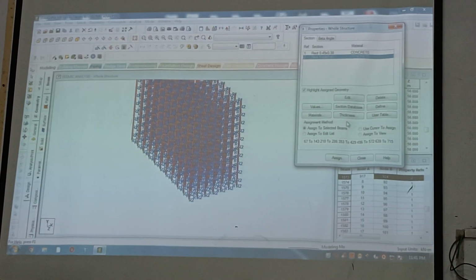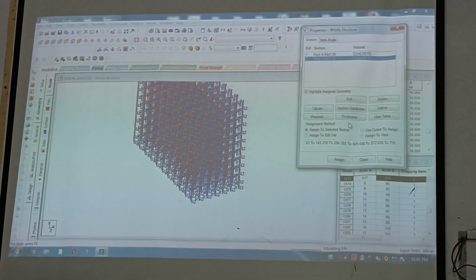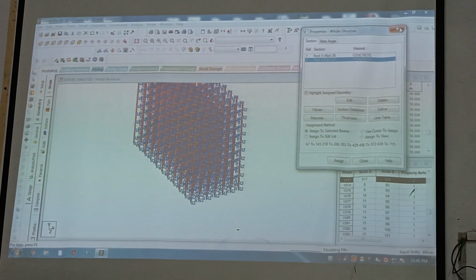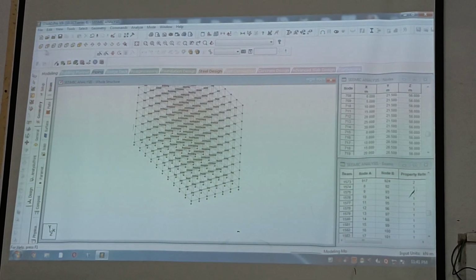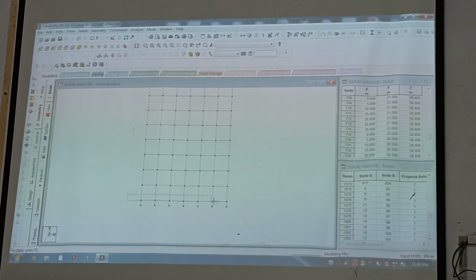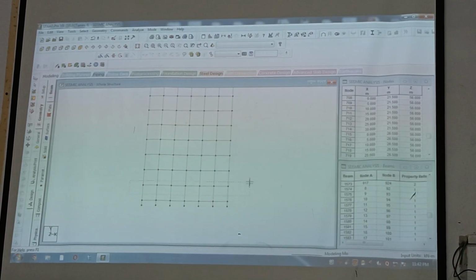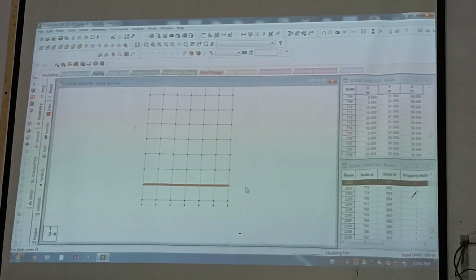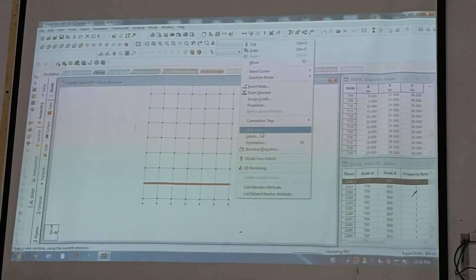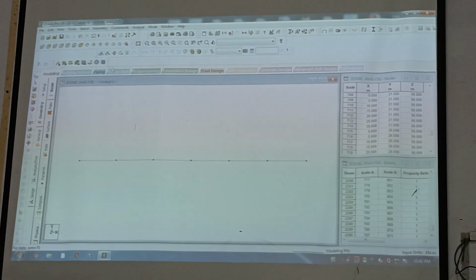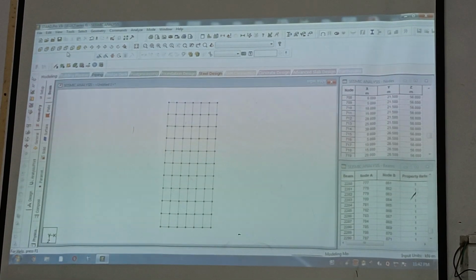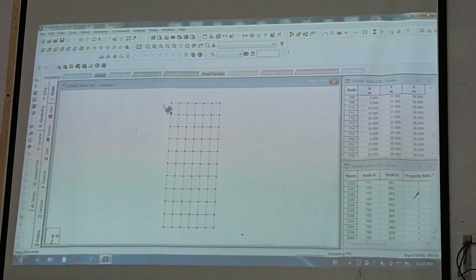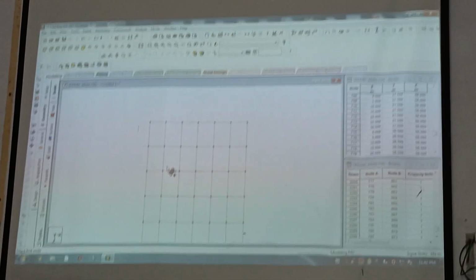What next? Support. But there is one more thing, right? Plate thickness. Plate thickness we have to add, right? So adding plate thickness, first we need to add the plate thickness which are coming in the structures. Select the floor in which slabs are coming. So you select only these beams with ground floor height beams. Okay, so first we need to add 4 loaded plates for individual panels.